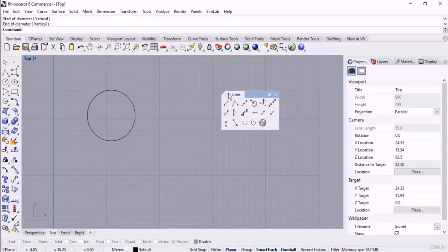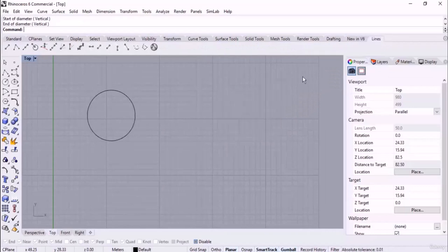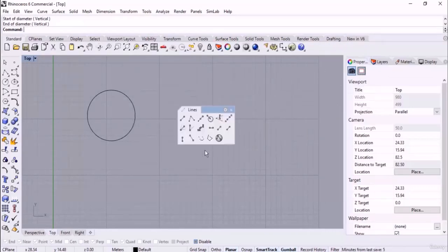And about the other approach for moving the dockable window, it is to click on the name of the dockable window. Then if you click on it, it can be included in another dockable window. I mean, we can include it in another panel. For example, if I want to add line as one of my standard toolbar tabs, I click on the name and then I drag it, I release it on the standard toolbar. Check this out, again I can bring it back.